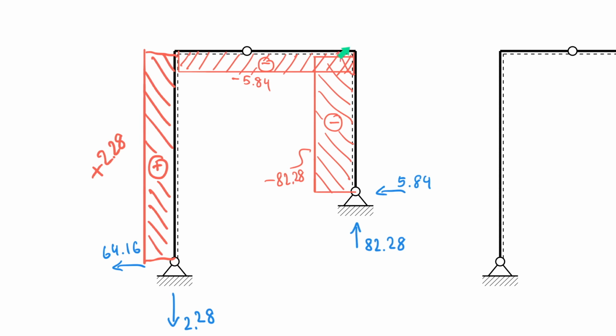You can convince yourself cutting here and calculating the normal forces and so on. So what students often do is they want to somehow connect this point, like the horizontal to the vertical member. Please don't do that. Look at them individually, if you will. Or if you're in doubt, make a cut. Same thing here. They are independent of each other, if you will. Of course, we will see something related now when we talk about the shear force diagram, but for now, that is what we're looking at.